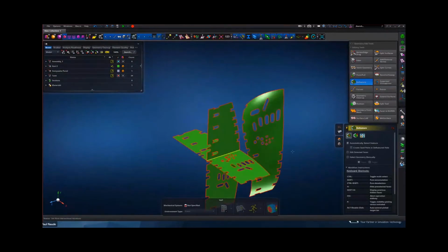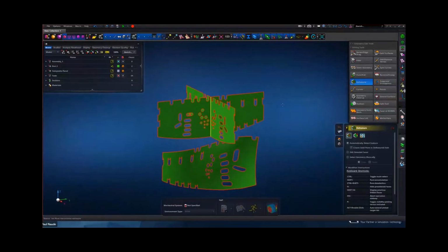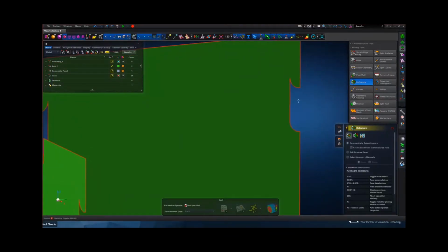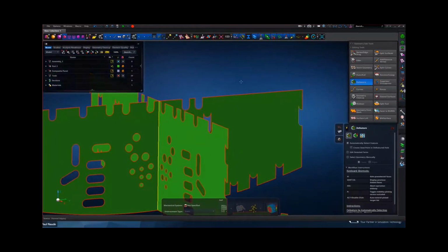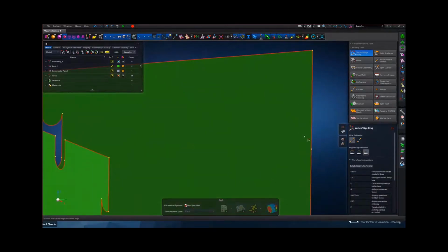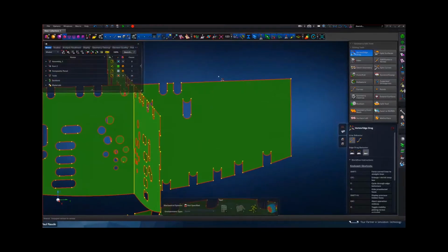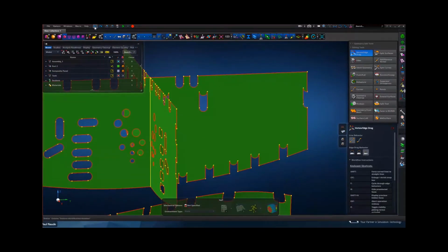If I showcase my solids, these particular surfaces. Now, manually, you can go in. If it's a closed loop system, you should be able to just select one edge and it cleans up the whole thing. In this case, it's battling a little bit more because these edges don't really form a closed edge. But if we switch off the automatic selection and select these, we can try and select it. In this case, that didn't work either. So then your only solution would be to use the edge drag tool to get rid of it. Okay, but that's only fun up to a point,